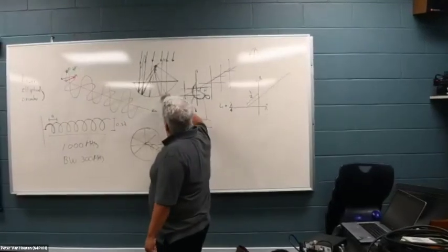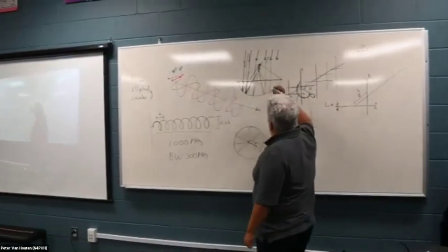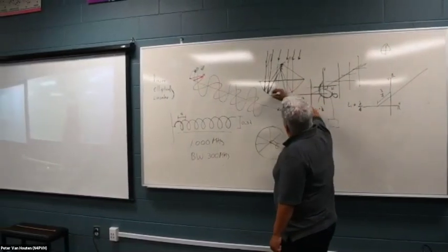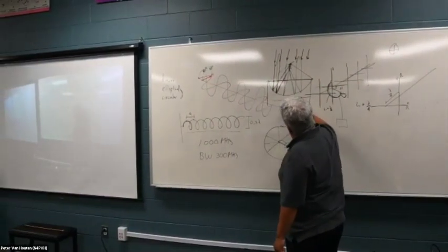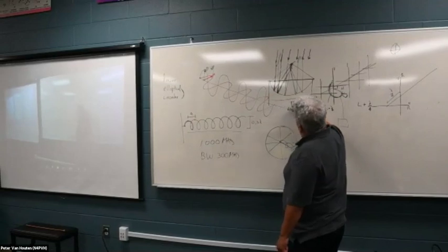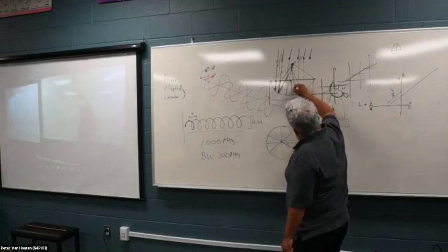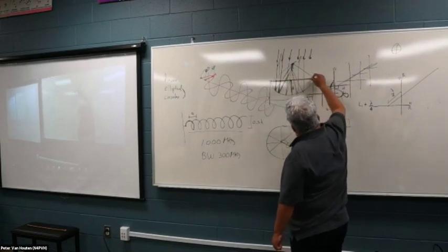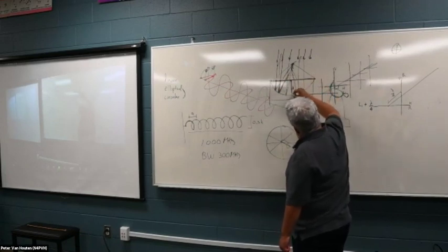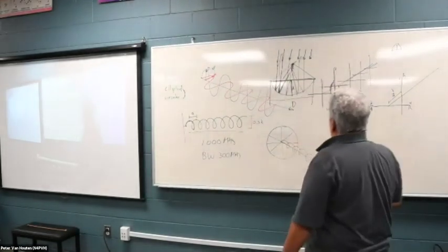Okay? One last thing on the parabolic. The two main design parameters of the parabolic are the diameter of the dish, which is capital D, because there's another d, which is the depth, meaning the distance from the plane that contains the mouth to the bottom center of the parabolic reflector. That's lowercase d.